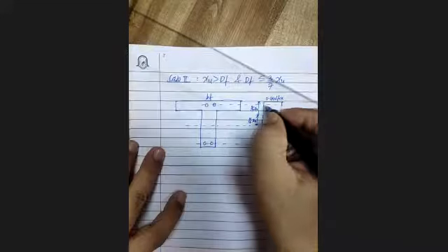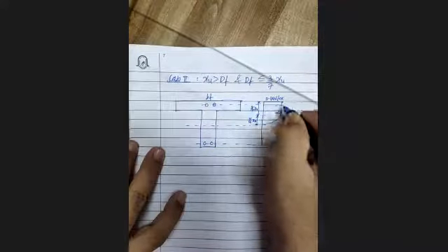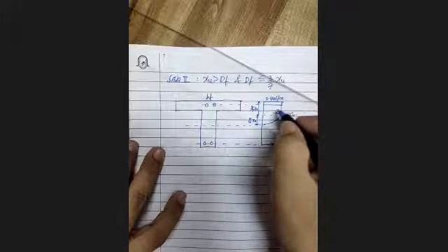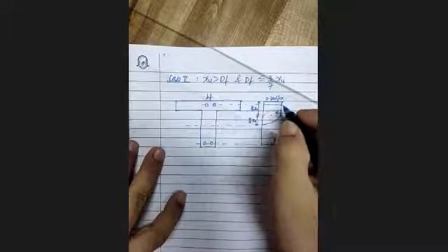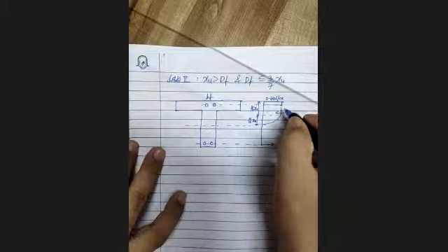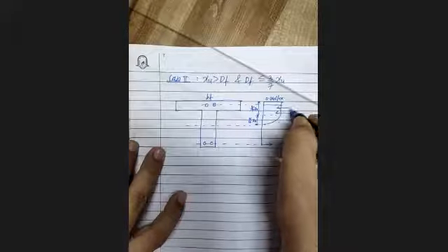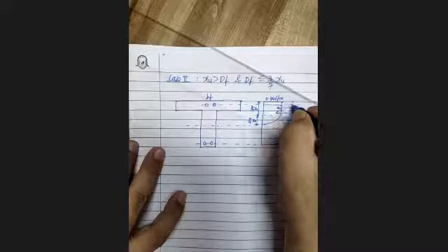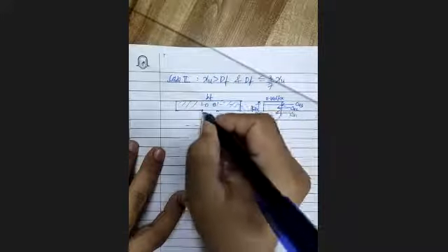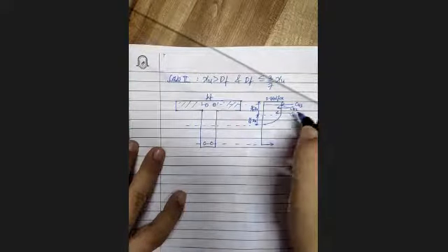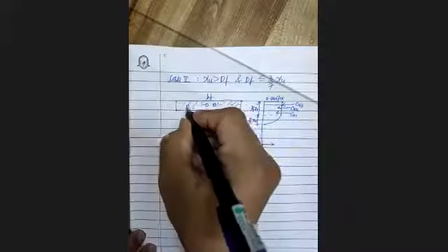So this compression reinforcement, and Cu2 will be for this flange, if you remember. Let us say this is Cu2, and for this compression steel we will have Cu3. Remember, we had considered these separate areas. So this Cu2 is for the flange portion, the second area basically.